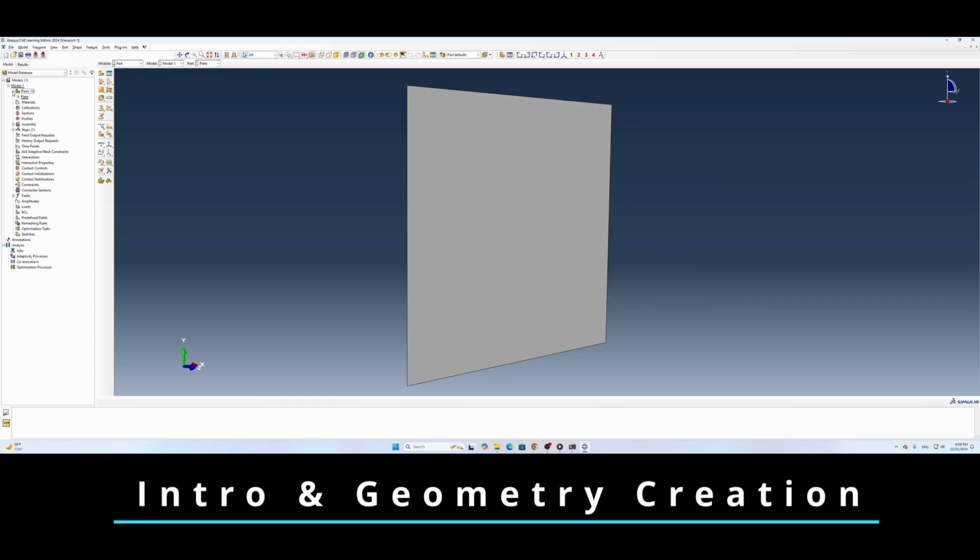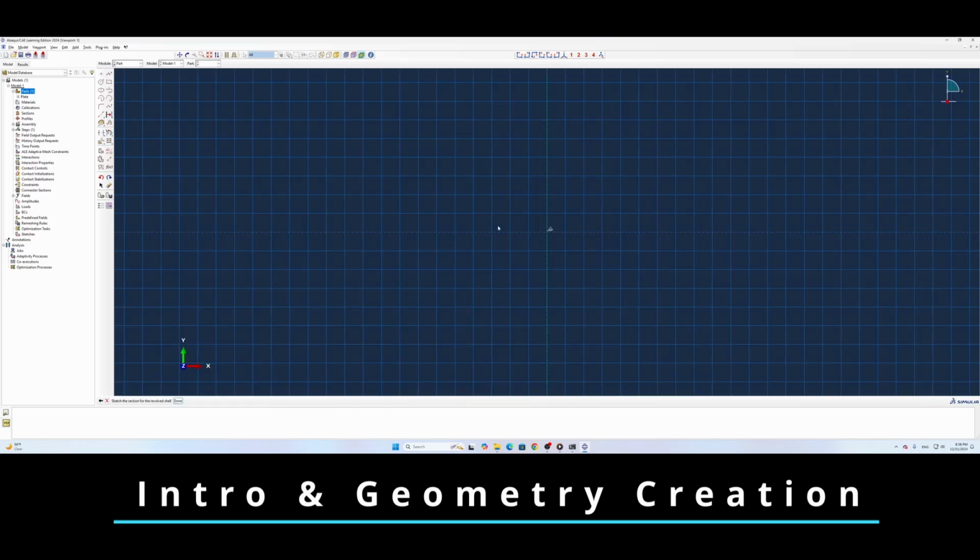The next part is our ball. Right click, create, and then the name is going to be ball. I'm going to use the shell function again, and I'm going to use the revolution. The approximate size, I need that to be 10. I don't need 200. So continue. Then I'm going to draw a circle from our center point here. Then we can again use the dimension function. The diameter I need is 4 millimeters.